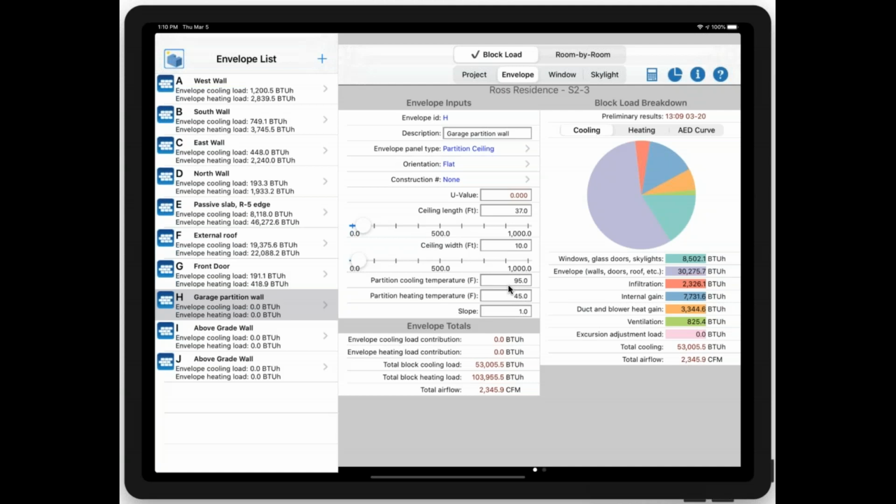And I had one situation where, it's my understanding that in New York City, the heating load should be heavier than the cooling load, but I'm consistently getting like 40,000 BTUs cooling against 30,000 BTUs heating, which doesn't strike me as correct. So I think I'm going to go back through and see if I'm missing something. I mean, I don't know. Can you really compare cooling and heating loads?